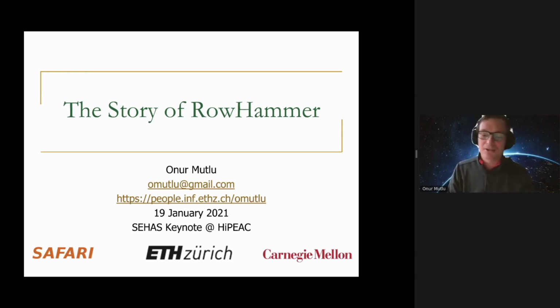And random can actually lead to a lot of overhead. If you do it in a targeted manner, meaning if you actually somehow detect a Rowhammer attack, when you're suspicious, you can copy the victim rows to spare rows. If you're careful, I think the overheads of this could be low. We actually proposed this in an ISCA 2019 paper called CROW, copy rows. And I like that idea, but its evaluation requires some more work going into the future.